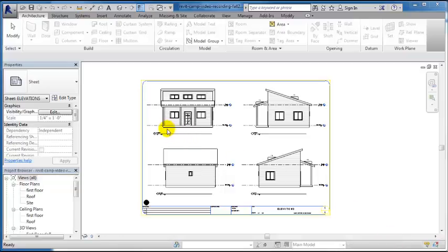I'm going to be adding a foundation underneath this camp. We're going to do a T-type foundation that's just going to be a crawl space with a full footing and a slab about 4 feet below the floor system. So the first thing I need to do is create a level for that basement to be defined at.